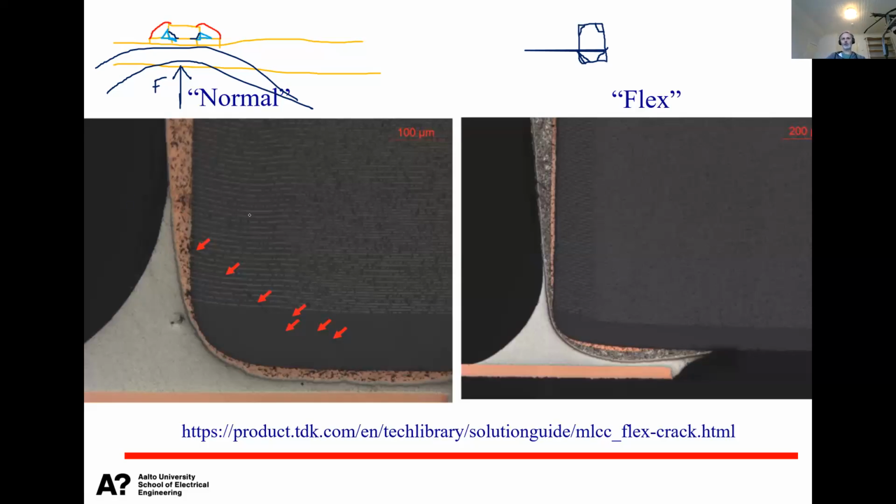In fact, why this was observed: these cracks came during testing. When they manufactured these printed circuit cards, they wanted to be sure that they are reliable. They pushed the cards in the bed of nails, and in that process, if one of the nails is a little bit higher than the others, it causes small local bendings. And that caused these corner cracks in these capacitors. That was of course a very annoying problem because you may not detect it immediately with electrical testing.